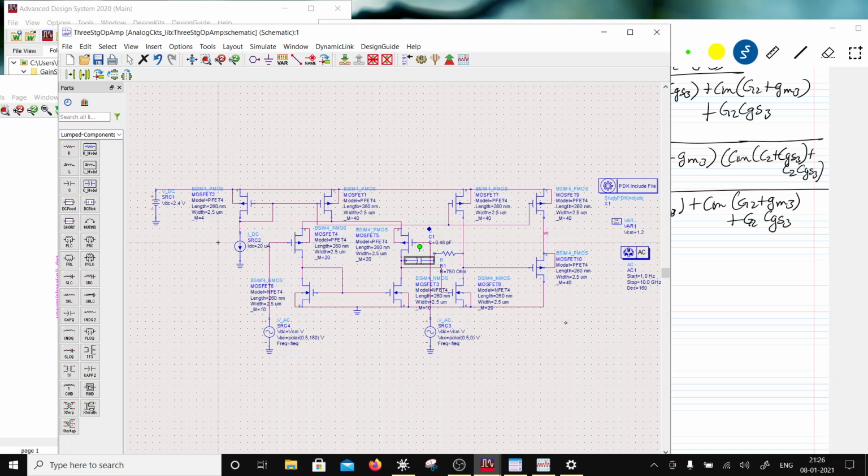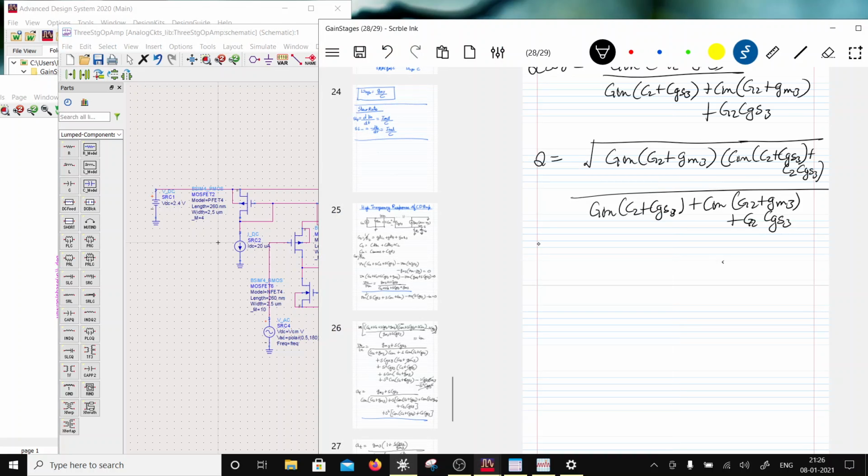So if you observe ringing in an opamp and the opamp has a final stage which is a common drain, then you have to hang an R and a C to ground. Anyways, you don't know the capacitances, so you would have to put RC here and tune, or rather you can just tune this and that will basically frequency compensate your output stage. So that basically completes the treatment on a common drain amplifier.